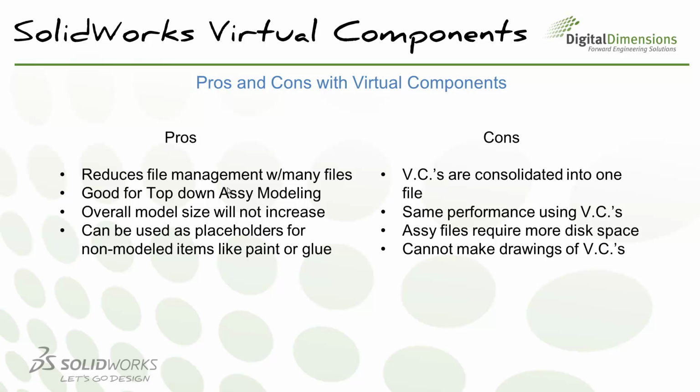The last con with working with virtual components is the fact that you cannot make drawings out of these virtual components. I did explain that you can go in and save these virtual components as separate items externally, so you can do that and it becomes a fully fledged part file, so you can go in and make the detailed drawings out of them.